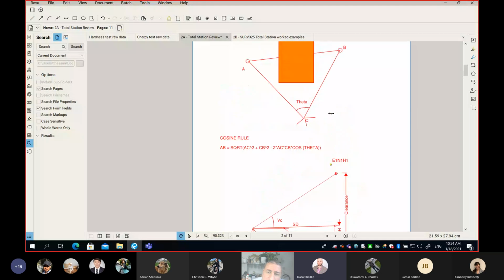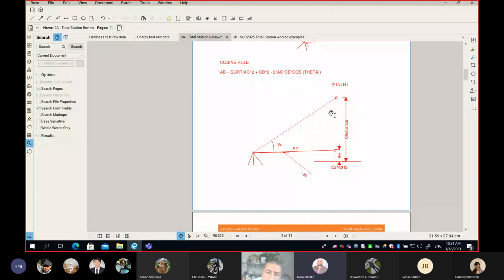Yeah, more or less. So basically, you have to be as close to underneath the point of interest as possible to get an accurate measurement. In many applications, people use their eyes to align themselves to the underside of the point of measurement. I know it's not 100% precise because you cannot be perfectly under the point, but do your best. If you are within plus or minus even 5 centimeters, then you should be okay. For the clearance estimate, let's be exact.